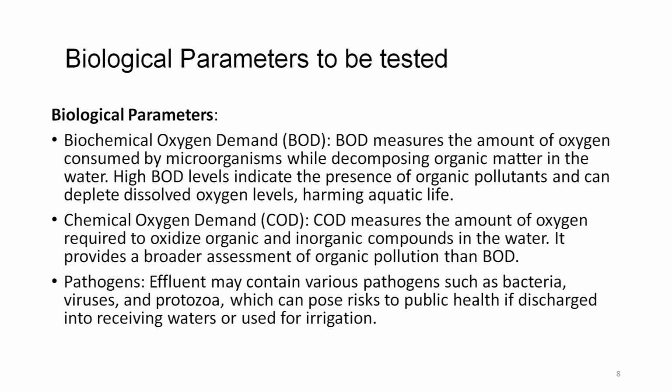Then biological parameters also need to be tested. Biochemical oxygen demand, which is BOD. BOD measures the amount of oxygen consumed by microorganisms while decomposing organic matter in the water. High BOD levels indicate the presence of organic pollutants and can deplete dissolved oxygen levels, harming aquatic life.